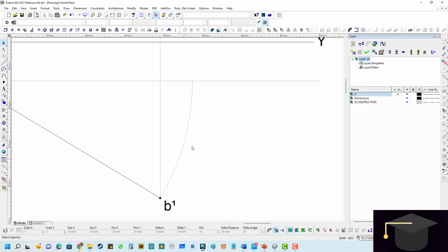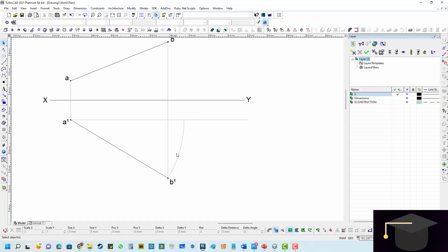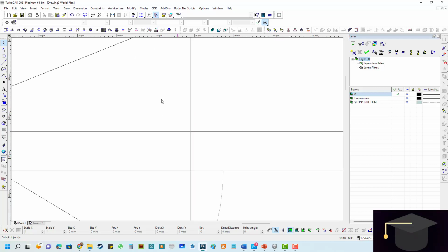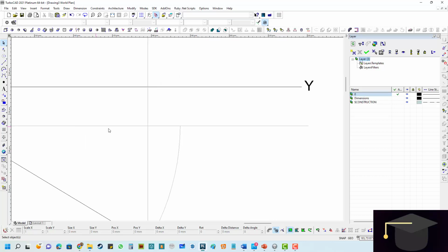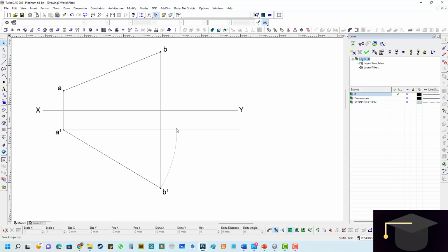You can clearly see how quick and easy on CAD I could have changed that color of our line to a construction line, which in this case I use gray for. And now what I need to do is from this intersection where that arc segment intersected with that parallel construction line segment, I'm going to draw a line perfectly 90 degrees upwards to my front view.